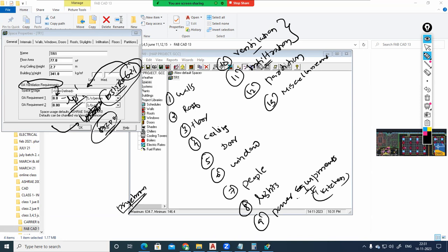Through all these regions, the hot atmospheric air will be entering within the space. If the space is pressurized, that can prevent it. We can discuss that. That's why if air is infiltrating inside, that is called infiltration. Whenever that is infiltrating inside, it is carrying sensible heat and latent heat from the atmosphere, plus contaminants as well. That's why whenever we are dealing with ventilation and infiltration, we have to do the psychrometric calculations. But the software will do that for you.